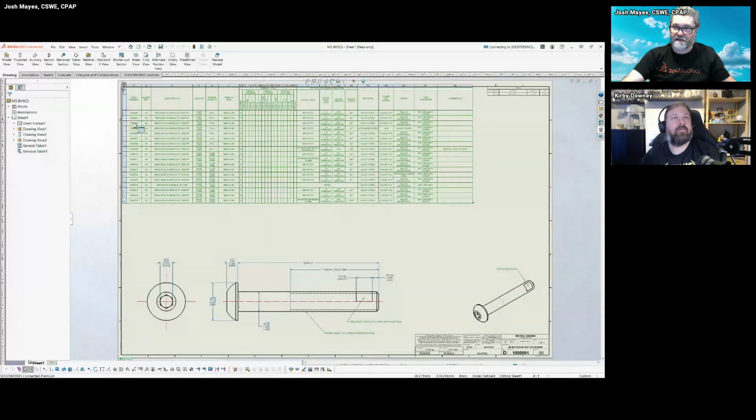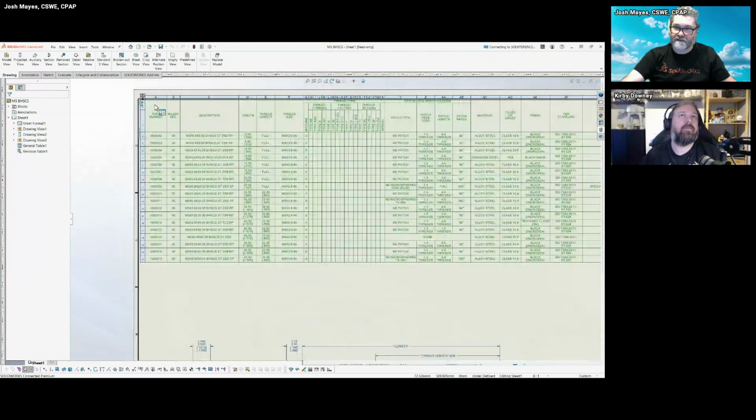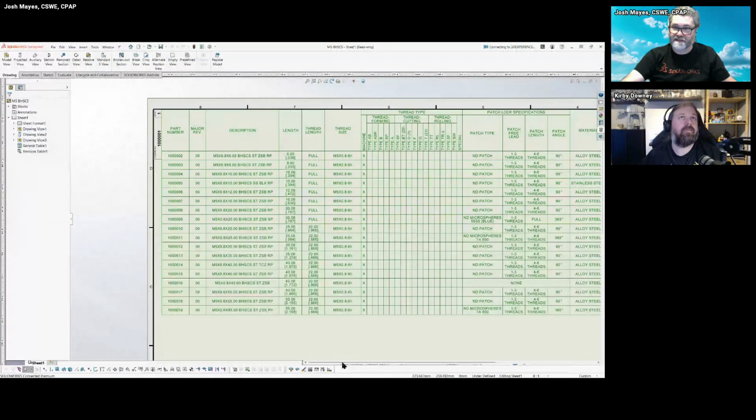And you can see, in terms of managing this on a drawing, we've got a table here that we've developed, and this table correlates to the design table. Now, there is a way to bring the design table directly into the drawing, but historically it's had formatting challenges. It's what you see is what you get. It was an OLE object situation where the Excel would directly be.